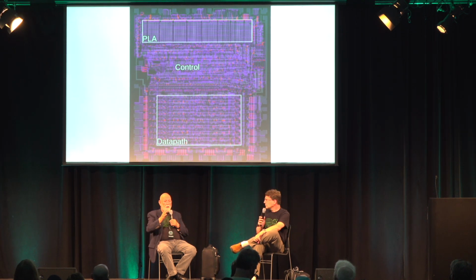6800 had an incrementer decrementer, 16-bit. And the reason why they had to decrement the address is because single byte instructions, it would click over to the next address space in the program memory. And so they'd have to back it up with a decrementer. So we came up with the idea of pre-decode.